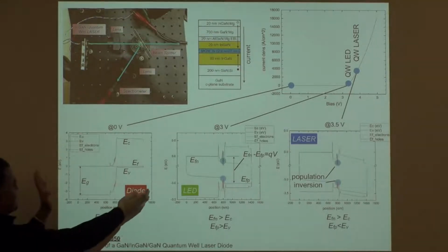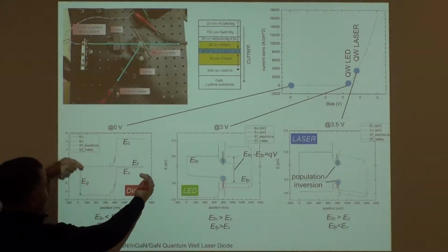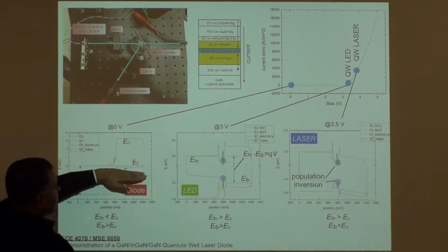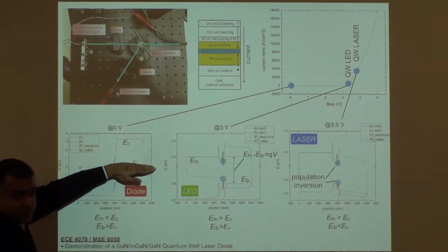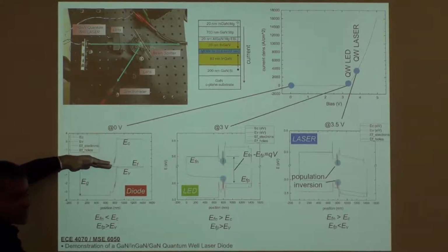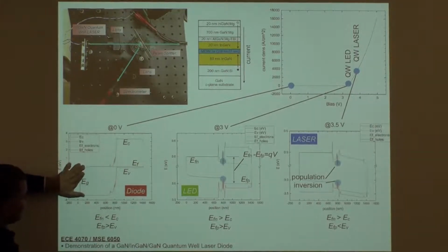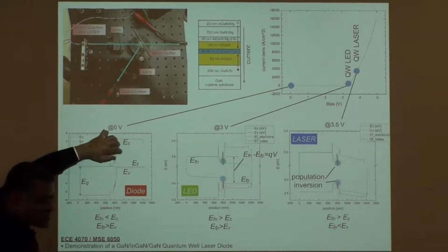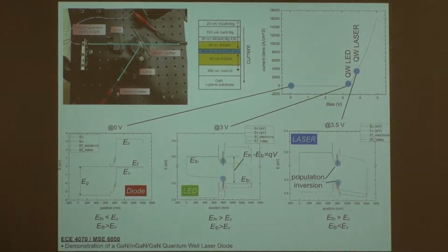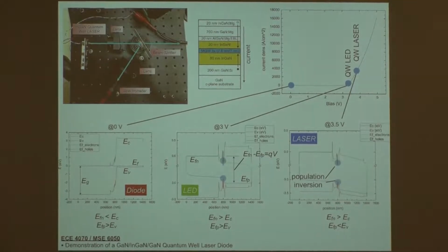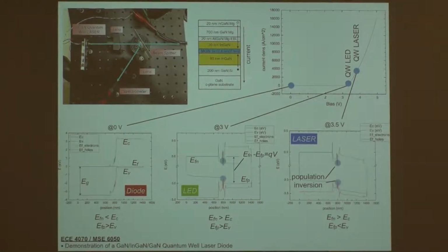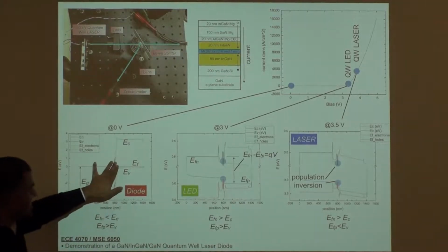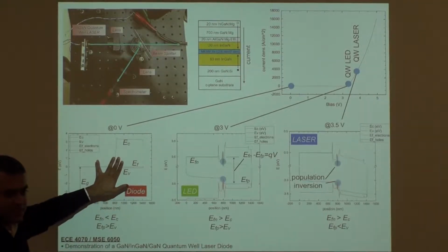You can calculate that when zero voltage is applied to this diode, your Fermi levels on both sides are the same. Here's your p-type valence band is close to the Fermi level, right? N-type conduction band is close to the Fermi level. Here's the gap. And you can see all these little tweaks here. These are the quantum wells that kind of go and shrink the gap in these small little regions here, right? And design the color of the light that's going to come out that way. You can see in this whole picture they're very thin, but they're extremely efficient.